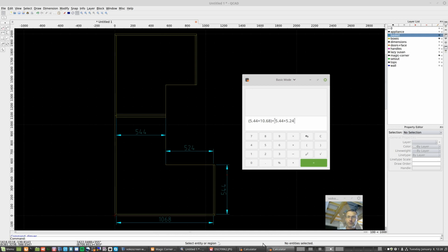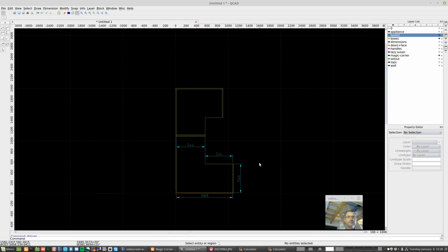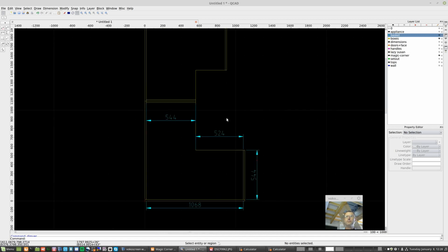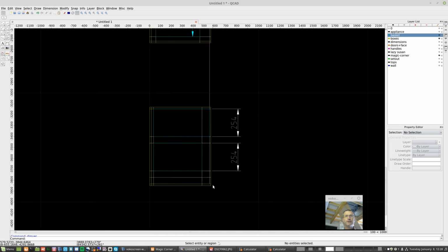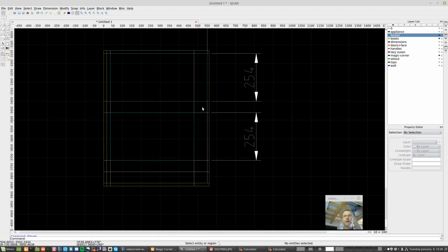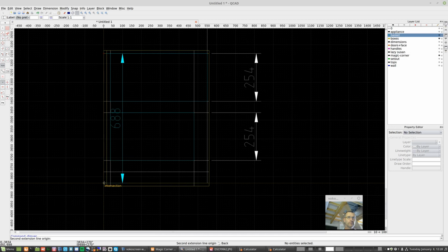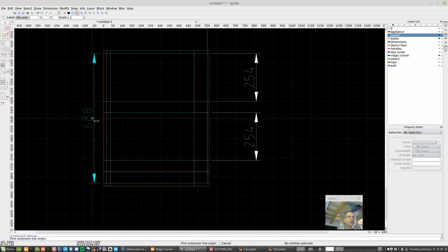Now we have to get heights, don't we? So we had, looking at this guy, oops, yeah, go down. Now the heights in essence are the same, except we lose the 25mm shelf plus the cleat. Let's call it 40mm. So that height is, then, if that's the case, this less 40. So that's going to be 640. Very simple.